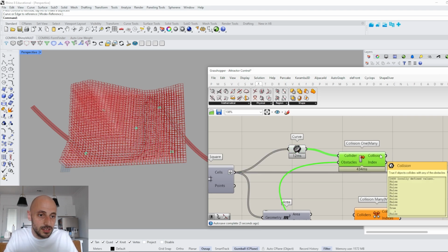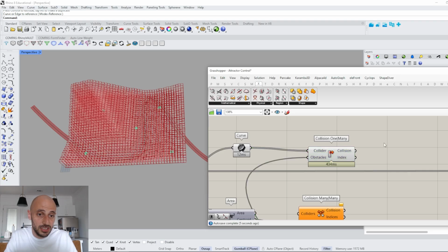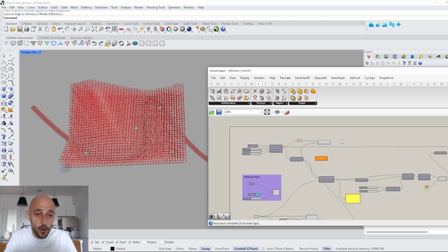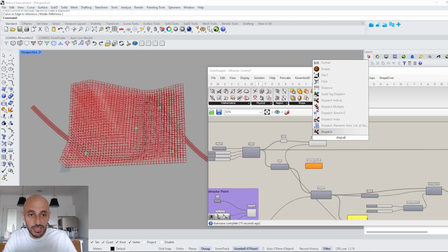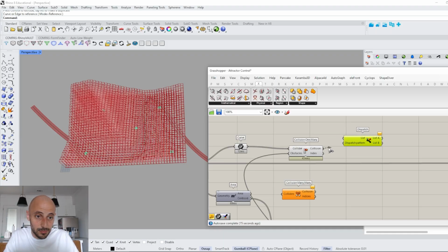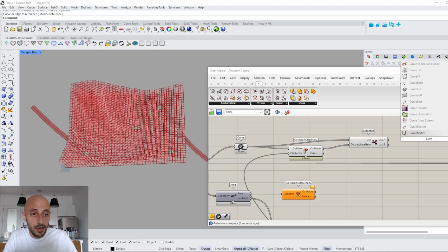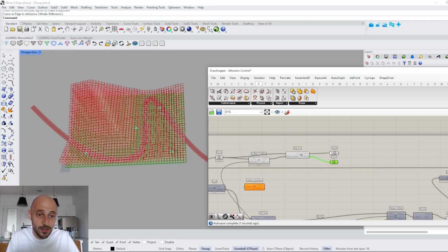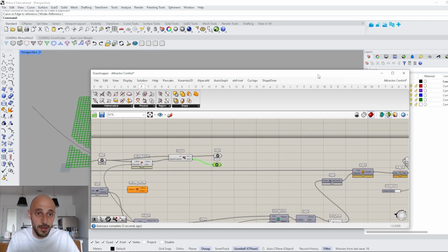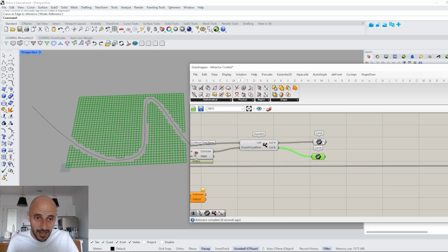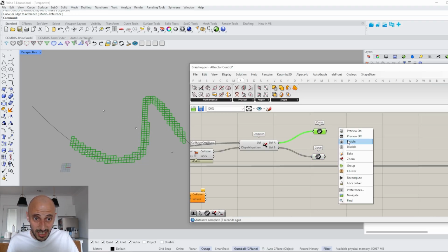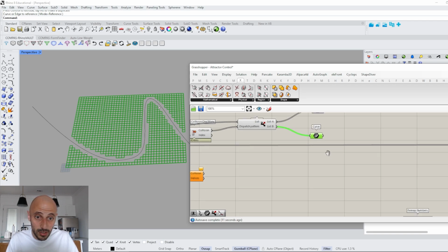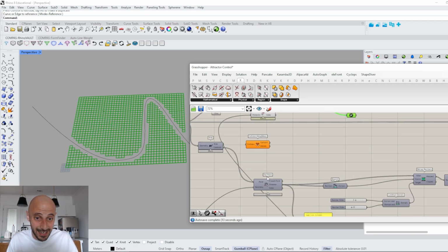And what we started to see is getting true/false information. What we can use this true/false for is basically this path, the curves that I have here as my pattern, and I can use this in, and it will give me the ones that are inside or overlapping or intersecting with my path, and the ones that are not intersecting with my path. So you see, these ones are the intersected ones, so I remove them. These ones are the ones that are not intersected, okay?